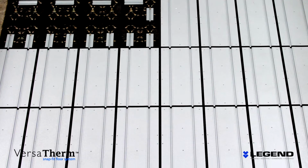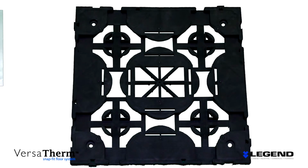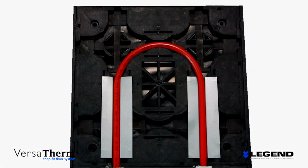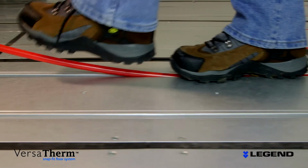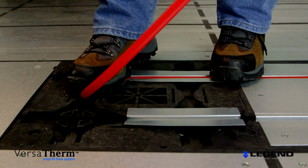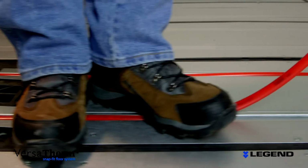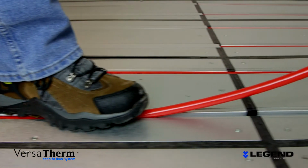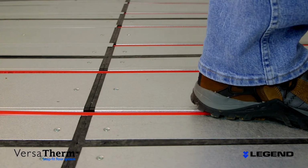Before laying down any tubing, inspect the tube channels and remove any debris. Diffuser plates are placed in the return panels. These plates serve as a channel for the tubing and to maximize heat output from the return panels. Following your tube layout design and starting near the manifold, walk the radiant tubing into place along the tube channels in the VersaTherm panels. VersaTherm is designed to use 1/2-inch PEX radiant tubing. PEX tubing, compliant with ASTM F876, will fit in the VersaTherm tube channels without the need of silicone or adhesives.